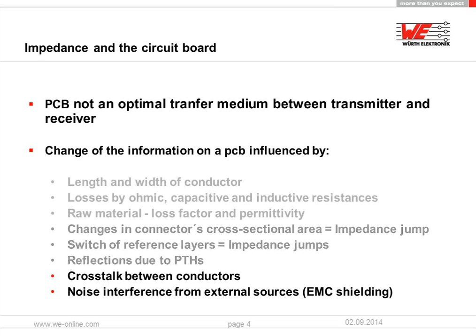Another important point is that using flex rigid there is a system advantage, as we have the disappearance of connectors and cables, so the signal integrity is quite a bit better compared to cable and connector solutions. Another small point is that using flexible material we have a really flat copper surface, and especially for high frequency signals this is another advantage. The skin effect is very low compared to standard treatment, which is very rough.